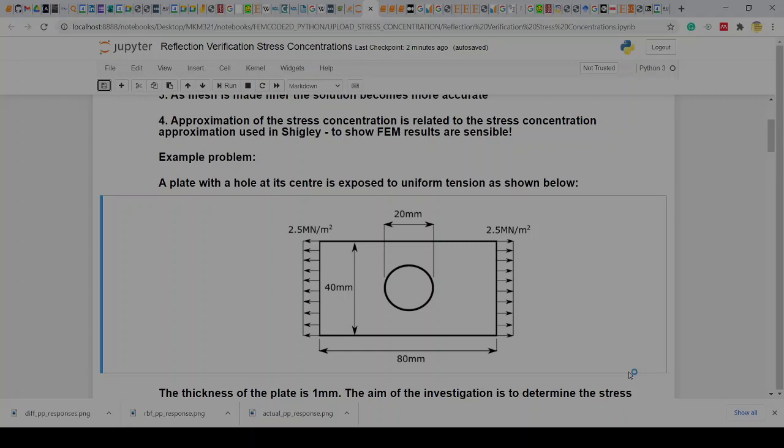So first of all, I just want to start off by saying singularity is typically where we have an acute sharp angle that you essentially try to pry open, so put into some form of a tensile opening mode. That will result in infinite stress because of the fact that we're modeling it linear elastically. So if you keep on refining that at a singularity, your stress will go to infinite. It will just keep on climbing.